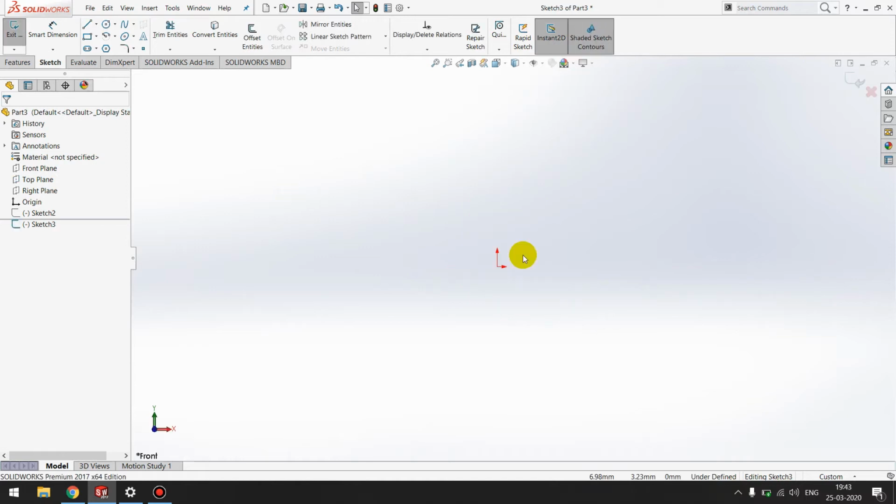So you can sketch a center based circle with the circle tool, or you can sketch a perimeter based circle with the perimeter circle tool. To create a center based circle, you can click on the center based circle. If you take a cursor on any command, it will guide you on what kind of command you can execute. So over here, sketch a circle, sketch the center of the circle, then drag to set the radius. So let's say if I click it,